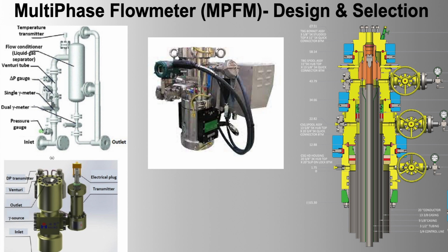3. Pressure and temperature. Inlet pressure, real-time pressure measurement at the flow meter inlet. Outlet pressure, real-time pressure measurement at the flow meter outlet. Temperature, real-time temperature measurement of the flow stream. 4. Diagnostics and alerts. System health, monitoring of flow meter health and performance. Alerts and alarms, notifications for operational anomalies or maintenance needs. Calibration and remote test capability.